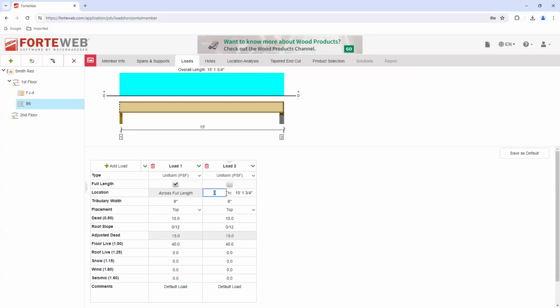So this one, I'm going to start it at 11-foot 1, and you can go 0.75 inches to the end of it. And I could have hit R, I could have done any of this, and then that one's going to be 8 inches, 15, 15. So you see how the diagram changed.